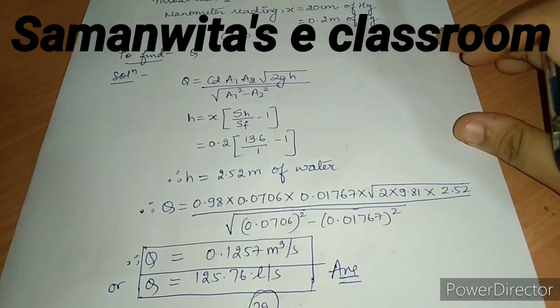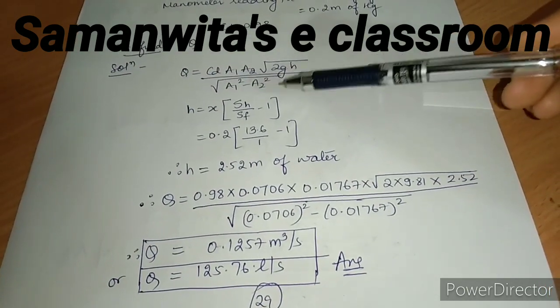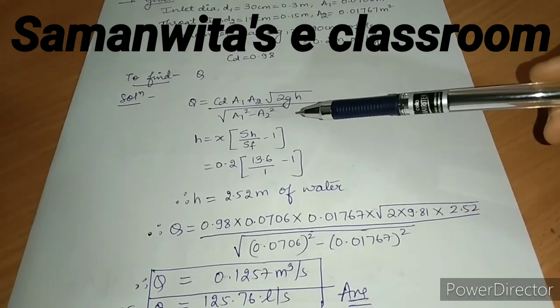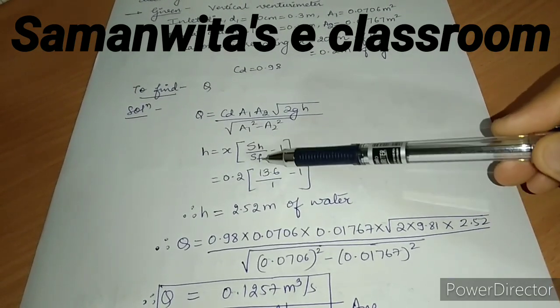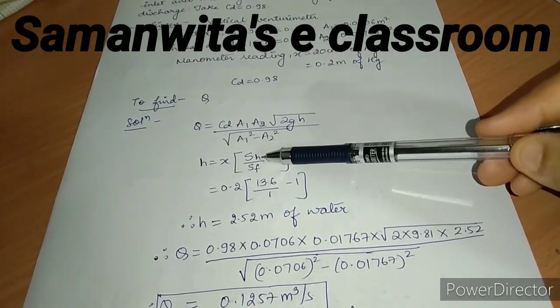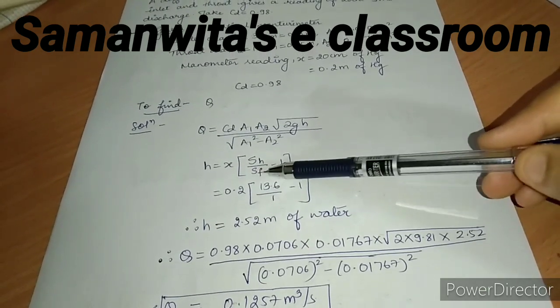You know the formula of Q now. It is CD A1 A2 root of 2GH upon root of A1 square minus A2 square. The formula in case of horizontal venturimeter and inclined venturimeter for discharge remains the same. The formula of H is also same, X into SH upon SF minus 1. I have the value of X, I have the value of SH, which is 13.6, and the flowing fluid being water, so the value of SF will be 1.